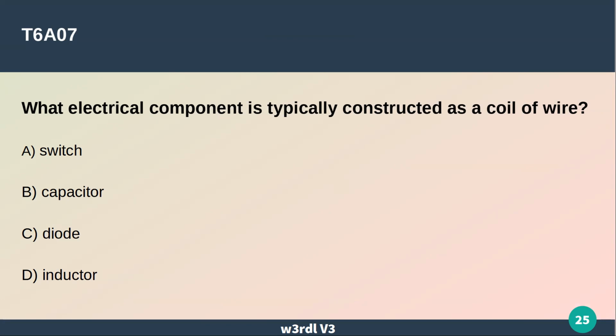There's the difference between a generator, a DC generator that used to be in cars, which used a commutator in order to make the contact, because they had to change the field as it rotated. In an alternator, it's a polyphase generator. I don't know if they're using 6 or 12, whatever, but they go through diodes to rectify it back to DC. So you're actually getting pulsing DC out of that alternator.